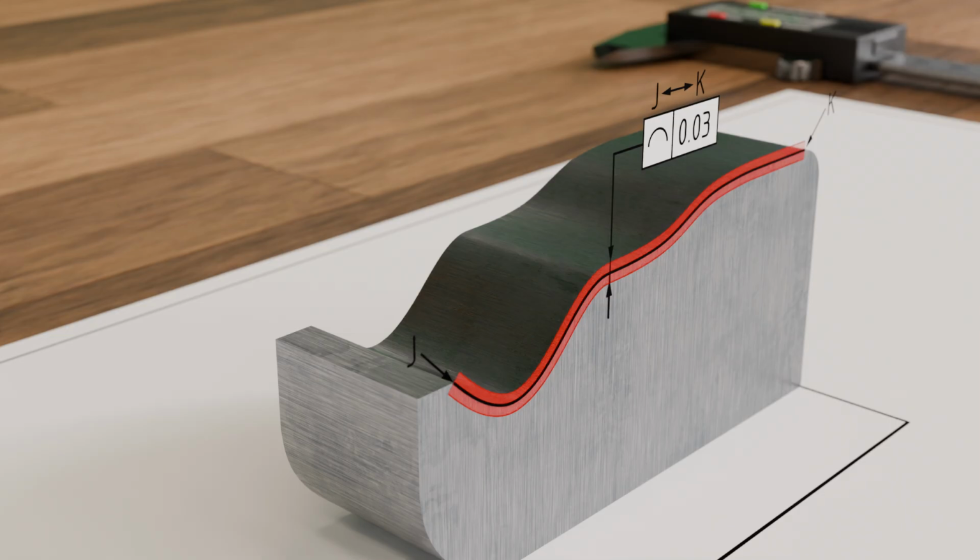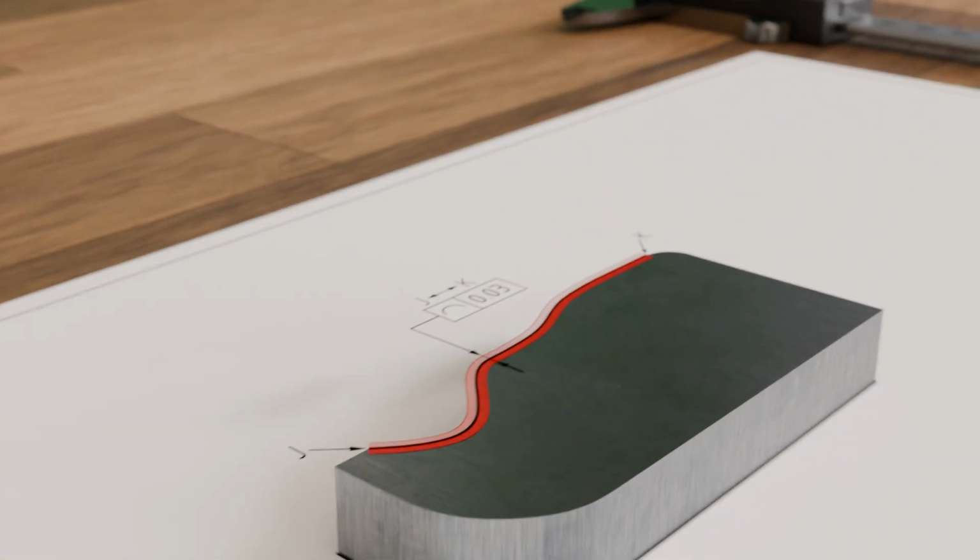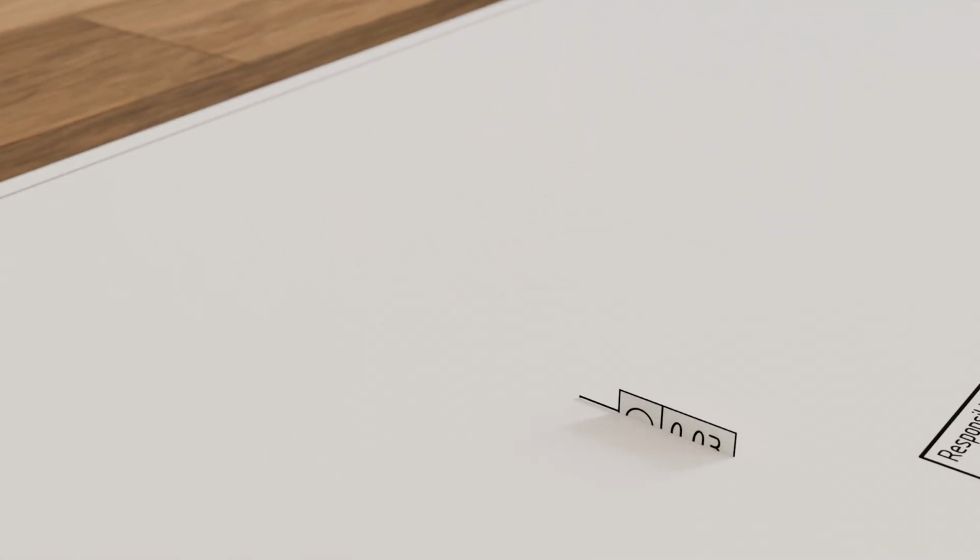This is only possible if the nominal line profile remains constant, meaning the front side of the component is simply extruded backward. In this case, the surface changes only along the line profile, but not perpendicular to it. The cross-sectional planes perpendicular to the surface then form straight lines. However, let us now consider a component whose surface is curved in arbitrary directions.